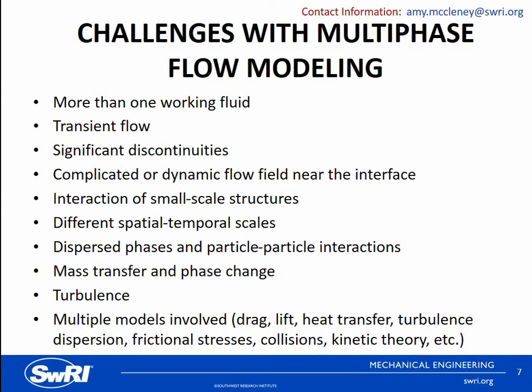So besides the turbulence model, you also have multiple models that look into the drag, lift, heat transfer, some frictional stresses, collisions, kinetic theory, etc. So there's so much physics that has to be considered, and that's why it's difficult to capture multi-phase flow accurately.